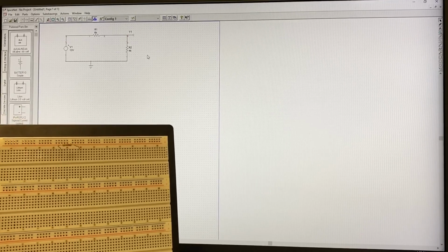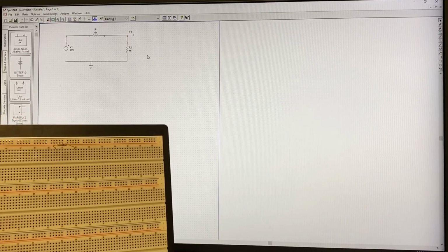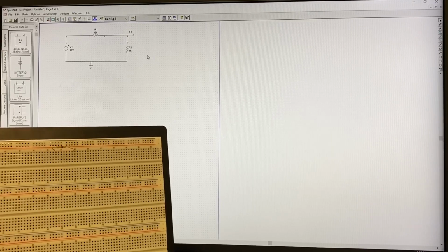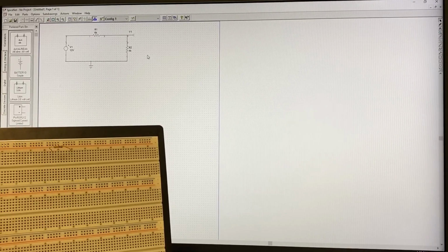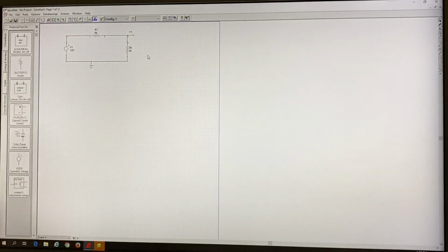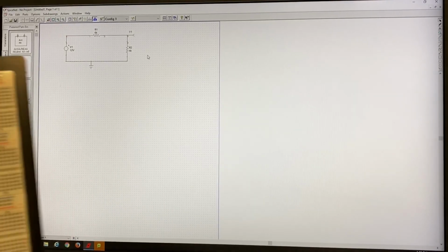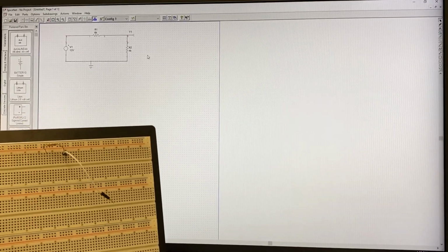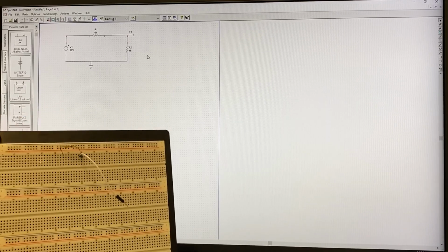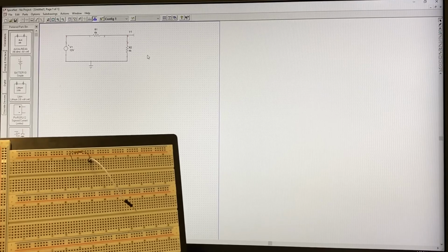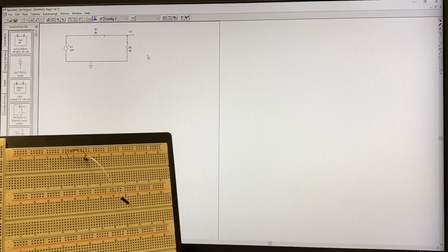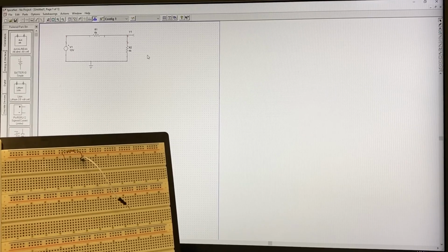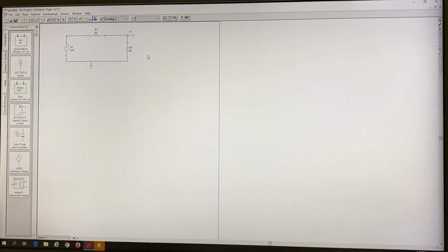Instead of you actually taking a measurement directly on where the resistor is, like connecting maybe a crocodile cable on the resistor, I'm telling you to add a cable so you can connect the crocodile cable at the end of that white cable. You see? So that's a test point. I'm just saying you're going to use that node at the end of the cable to actually record. That's it. So it's nothing complicated, but for now, let me just put it, right?